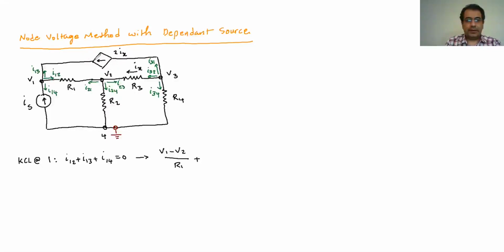You'll see that in that wire we already have the current source. So we know the current in that wire is going to be 2Ix. We don't know how much Ix is, but we know the current is going to be 2Ix, going from right to left. So the current in this wire is always 2Ix, and it is in the opposite direction of what we assumed for I13. So instead of having I13, I'm going to put negative 2Ix, because it goes in the opposite direction of I13.